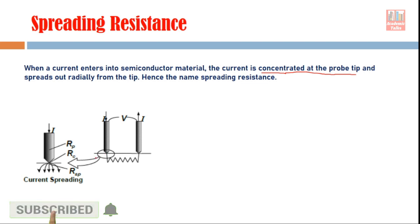What happens here at the top, when the current enters into the semiconductor, it spreads outward like this. See, the current is entering at this point, and from this point the current is going outward. It is moving in all possible directions. So this spreading happens here at the interface inside the semiconductor, and that's why this current is known as spreading current. And whatever resistance is offered by this interface and this portion of semiconductor to this spreading phenomenon, that resistance is known as spreading resistance.